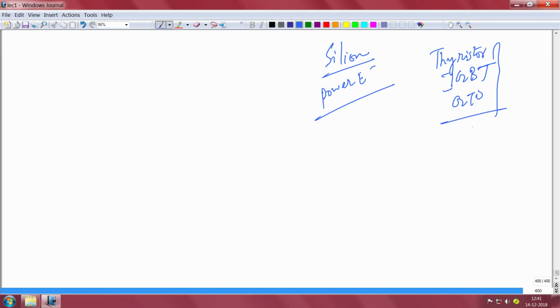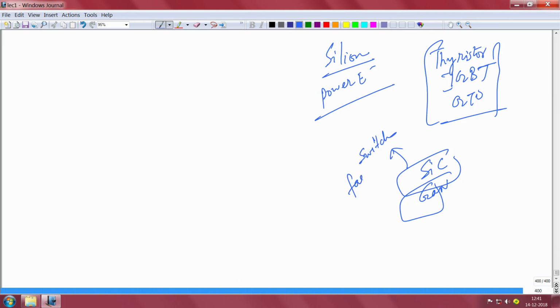can convert power. Of course, there are new technologies like silicon carbide technology and gallium nitride technology, which are also challenging silicon's dominance, and they can not only give the same or higher breakdown voltage at the same on resistance, but they can even switch faster, especially gallium nitride. So, when you want a fast switch that can also block kilovolts and carry amps of current, gallium nitride or silicon carbide might be better than using a silicon device, but the silicon device wins on cost. So, there is no comparison to that there.